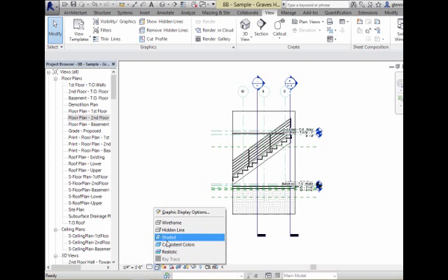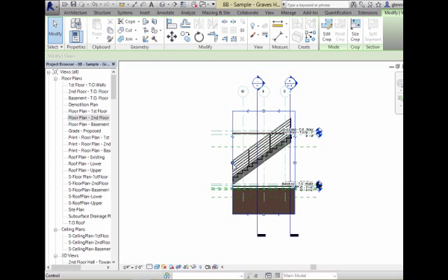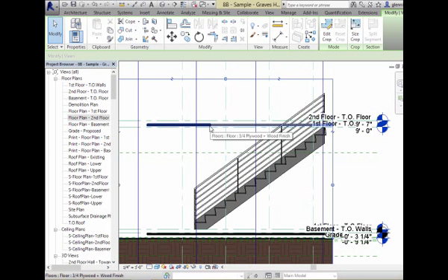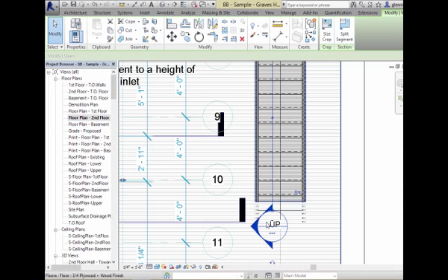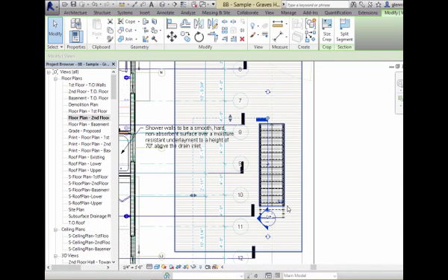You can kind of shade that. See if we can figure this out. It's a little hard to see because that's actually the edge of the floor. Let me adjust the section a little bit, just to show you how you might fix that. On this section, sections have this notion of a range, how far out you want to look. If the answer I'm trying to get is really just about what's happening in the stairwell, I can pull that range back very close to the section line.